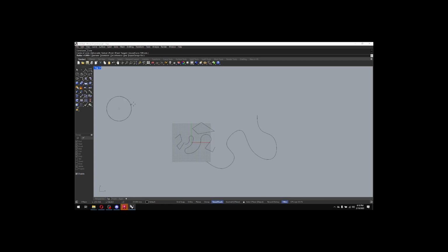Circle, that's going to work just like it does in CAD. Typically, we'll start with your center point. There's a lot of other options in here you can use. Like I actually use this 3-point a lot when I'm trying to figure things out, like size or radii of things. That one's really handy. This is what I like about Rhino, it's got a lot of these mathematical ways to make shapes based off of a variety of points.